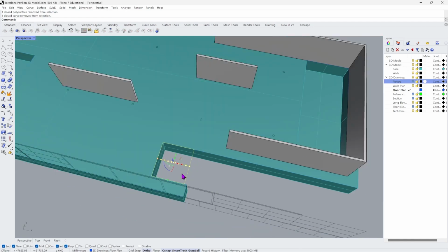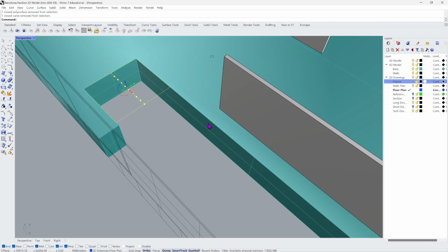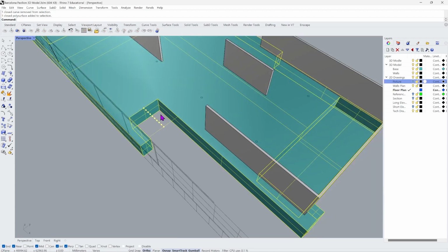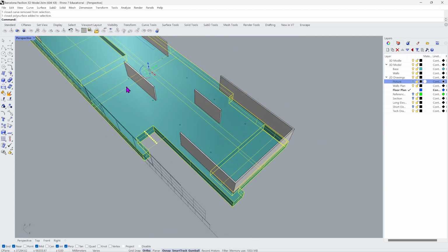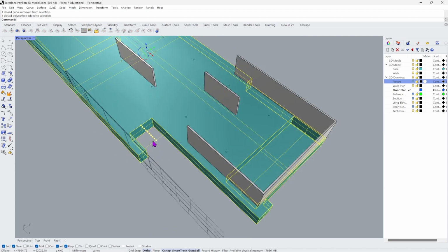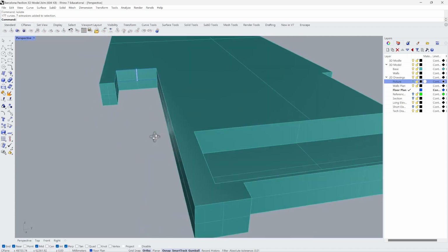And I just need to start working with my stairs. I'm actually going to select the base and keep it there as well, just in case. And everything else I want to hide. The easiest way to do this will be to type the command isolate, which means that it will hide everything else except the object that you currently have selected. So isolate, press enter, perfect.